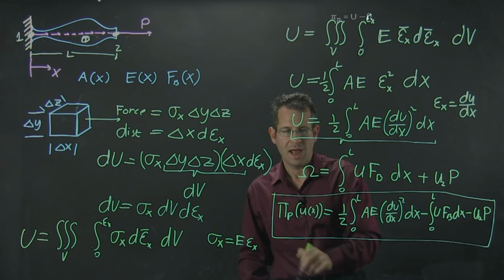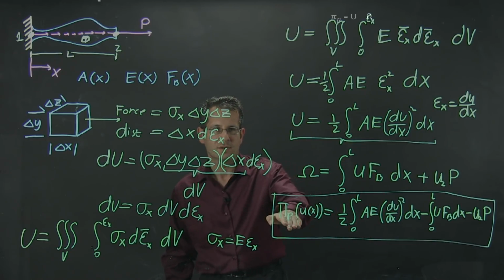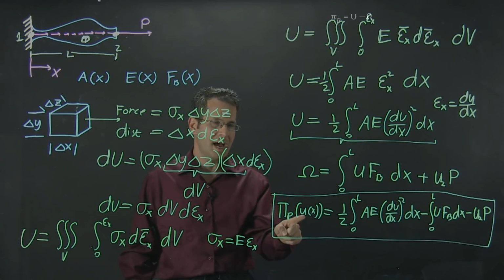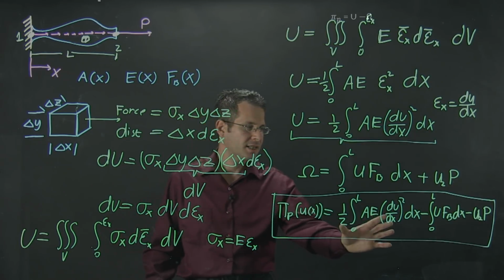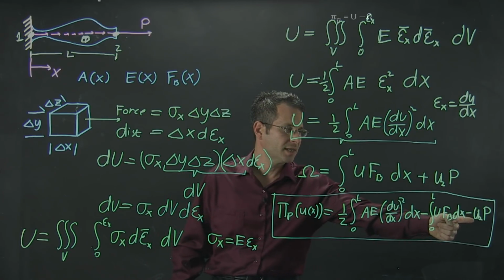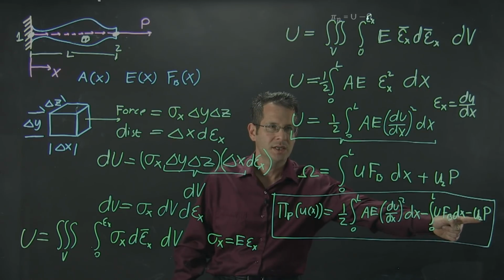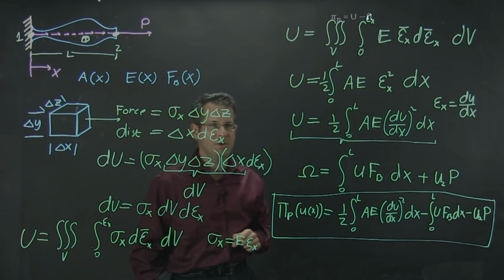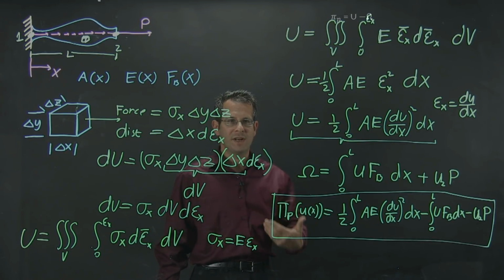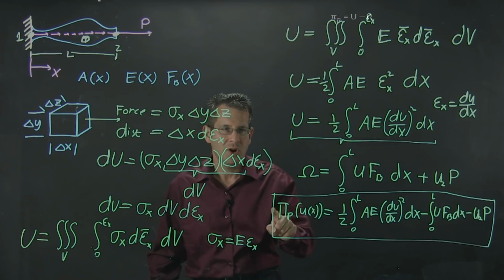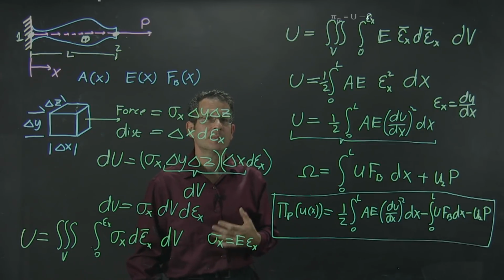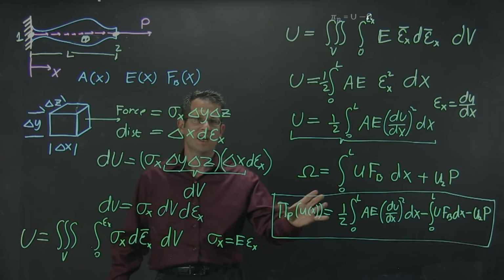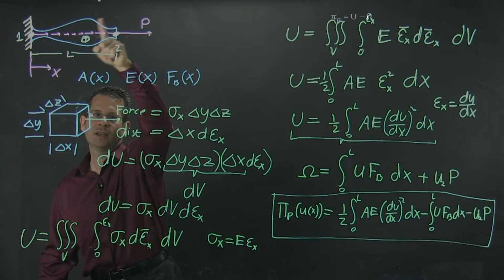Okay, so now I have this function of total potential energy stored in the system as a function of the displacements of x, as this integral minus the displacement at node 2 times the force applied at node 2. Right. In the next video, we will find an approximation to this value, which will allow us to apply the principle of minimum potential energy and to find a solution to this general case of a bar element.